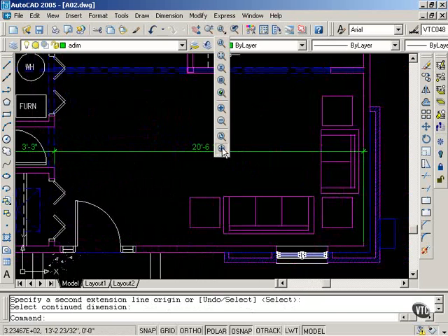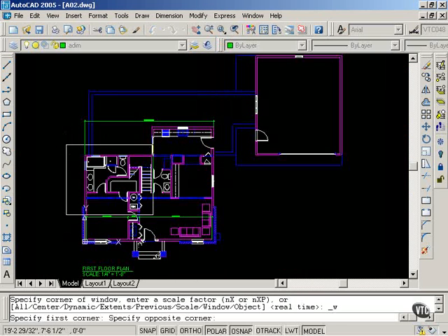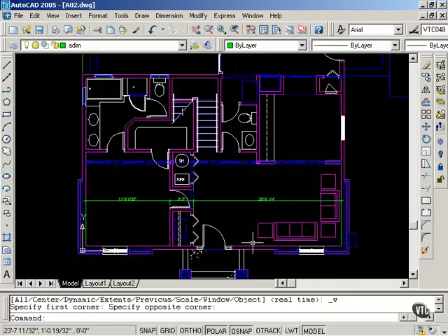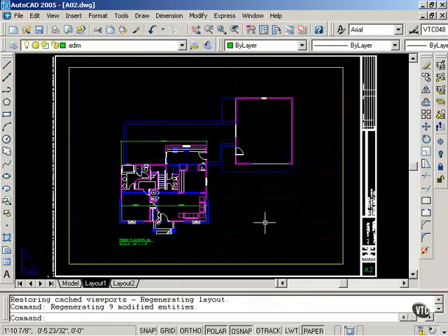Close this, zoom extents, and you can see how dimensions can be placed on the drawing. Going back to layout 1. To reinforce the external references, I am using the same floor plan and the same border for the architectural sheet and the electrical sheet, but I am placing different information in model space of each sheet.